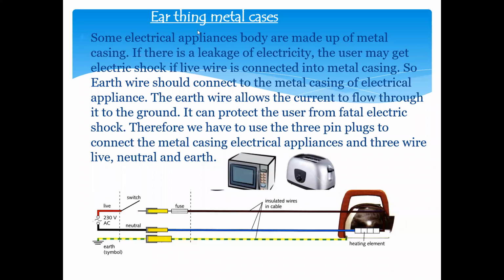Like you can see here, this is the safest way to make the electricity safe. We have a switch here, and we have a fuse to protect this kettle. And we have an earthing wire. When the current flows through the circuit, it produces heat energy, but maybe a live wire touches the metal body, so the current will return through the earthing as well. So if a person touches it, he will not get an electric shock.